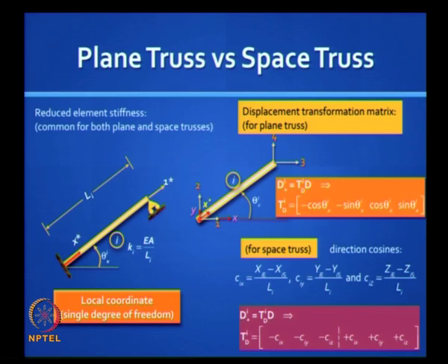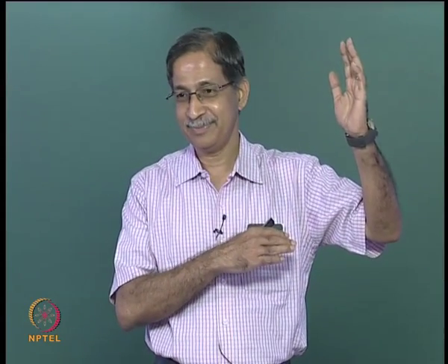That's all. Okay. So for a space truss, write down the 3 direction cosines. You don't have to write theta also. You just need the coordinates, because this is actually cos theta x, cos theta y, cos theta z. And then just like you had minus cos theta, minus sin theta, by the way, minus sin theta is actually a direction cosine with respect to the y axis. So you need the 3, the x axis, y axis and z axis, and you have minus.